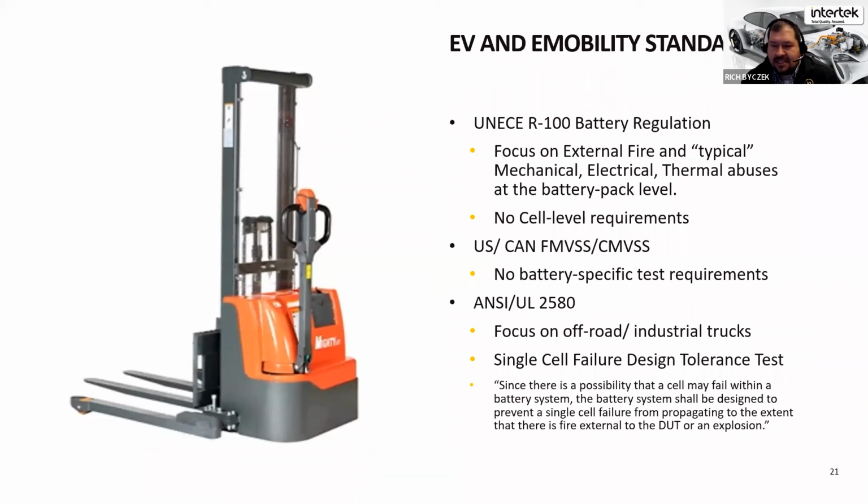I talk about the regulations for vehicles, UNECE R100. We do have an external fire test. We do have simulated crush and crash event testing there to look at how the battery prevents thermal runaway from occurring under those external stress sources. Doesn't address the internal short circuit concerns, but it does address some of those external sources that maybe are beyond the control of the driver of the vehicle. In the US, we don't have a specific EV requirement for propagation testing,